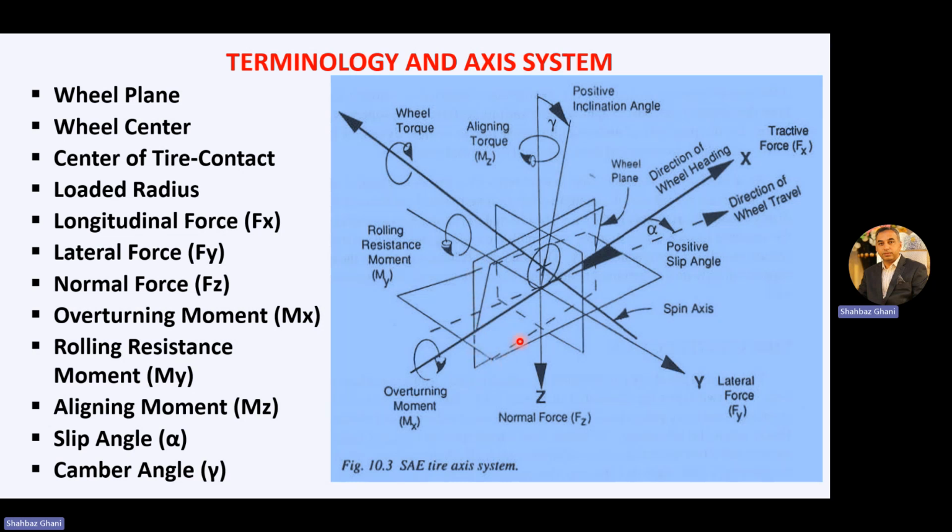Then we have this dotted line. Now, due to steering geometry, the camber, caster angle and the toe in, toe out, the tire is not in this plane. So the tire is moving outward. So we have to draw the tire plane also. So this is this plane.